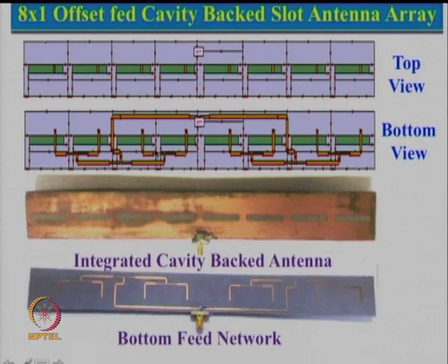So let us see one by one. Here we saw there is one slot antenna, and for this slot we need a microstrip line feed. So this is fed over here. Now we had seen that it was matched with a 50 ohm line. For this 50 ohm, we have used a quarter wave transformer, of characteristic impedance approximately 70.7, and we had seen that if you use the transmission line concept, this acts as a quarter wave transformer.